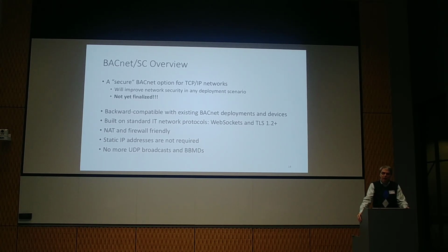If you don't have VLANs right now, if you're running your BACnet devices naked on an unsecured network, then of course I hope you're not doing that. But if you are, then BACnet SC will give you some added security in that situation. Another really important point is that we're not done with this yet. We're still working out some of the minor points of how BACnet SC is going to work.